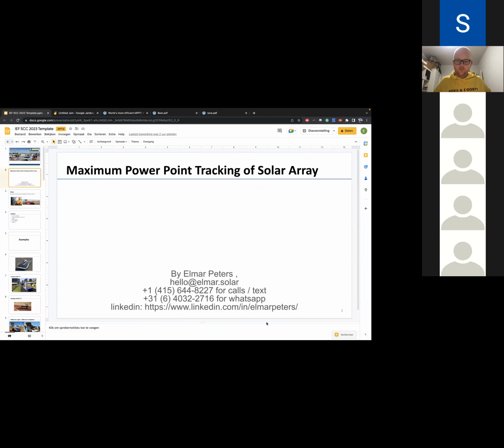With the interpretation of the IV curve of a module, let's say, it may mean you have to replace it. Replace a module? Yeah, because it may be irreparable. It might be broken, you mean? Exactly. So that's something you can learn with this. If you have damage on your array, then you need to... Or you can bypass a single broken cell to make the problem a little bit less bad.